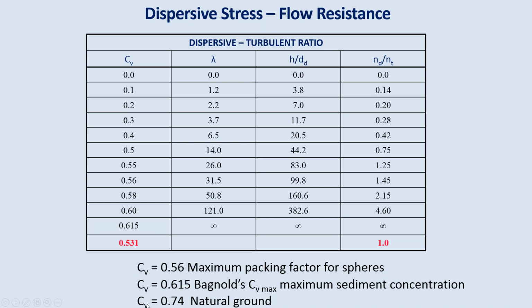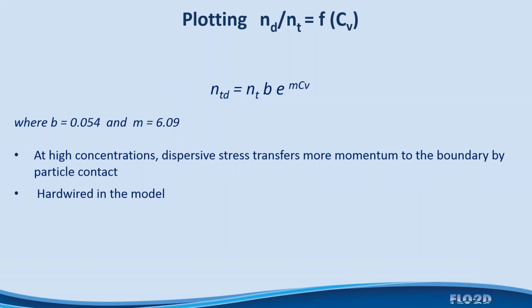So if you see people talking about concentration by volumes of 74%, what they're doing is including some of the boulders in the flow, probably in their concentration, but the boulders aren't contributing to the flow motion and the fluid matrix. So I would leave the boulders out, in which case this can't be anywhere close to 70% concentration by volume.